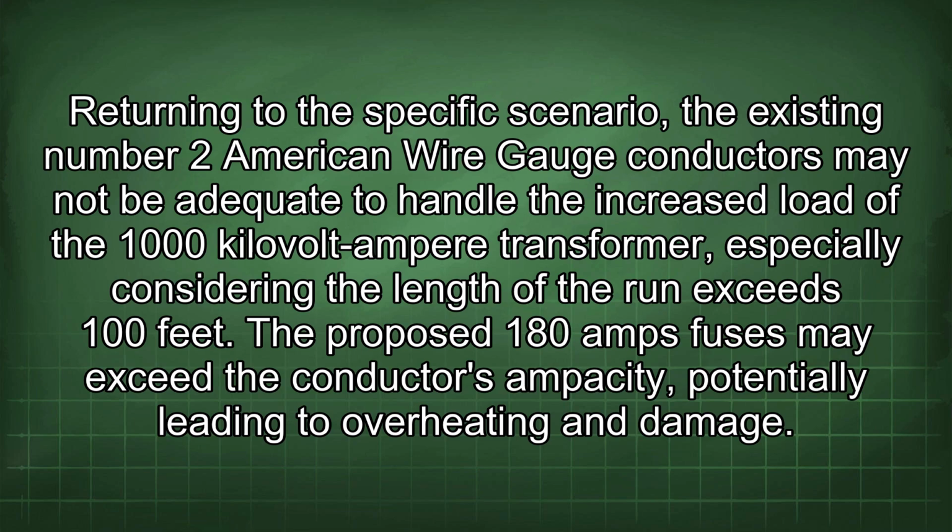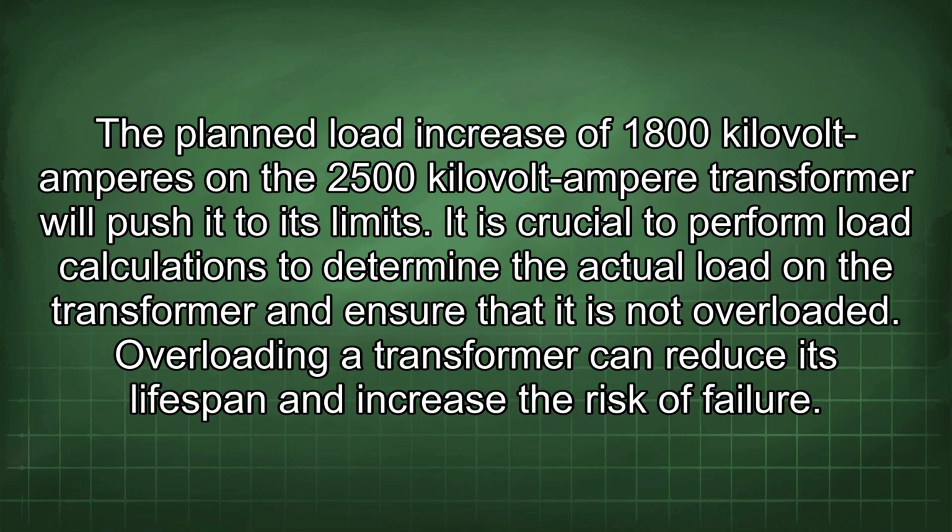Returning to the specific scenario, the existing number 2 American wire gauge conductors may not be adequate to handle the increased load of the 1000 kVA transformer, especially considering the length of the run exceeds 100 feet. The proposed 180 amp fuses may exceed the conductor's ampacity, potentially leading to overheating and damage. The planned load increase of 1800 kVA and the 2500 kVA transformer will push it to its limits.